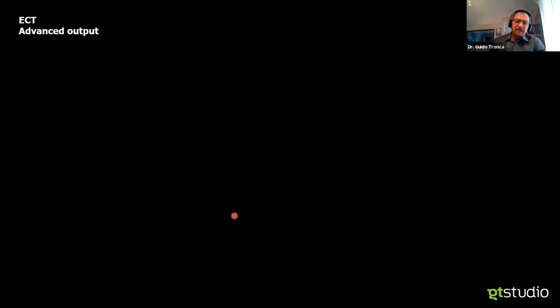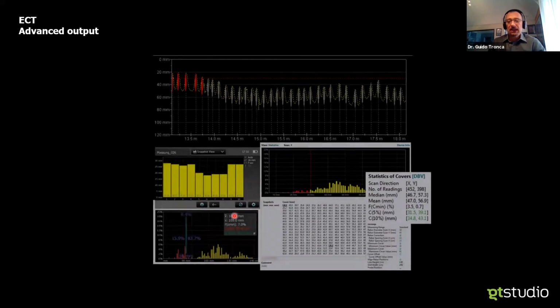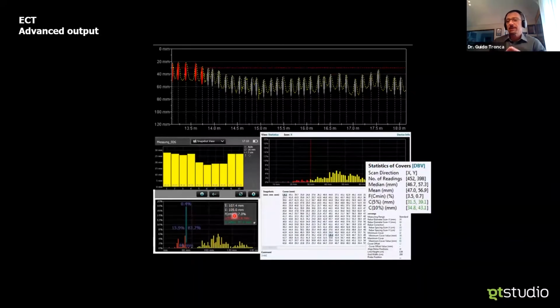But especially if we focus on high performance instruments, and let's assume you use an instrument with a wheel, like the Profometer, for example, then you will see its full potential for conformity check of cover. That is a mandatory check in many agencies or many general contractors. You want to check that the rebars have sufficient cover.